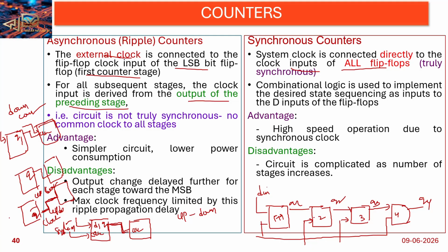So this is normal positive operation, that means active high operation. All are connected normally. This is active high, normal operation. Similarly, for active low, the up counter and down counter work like this. Q bar is connected to the next flip flop input. This is the down counter. When it is a down counter, this is negative edge triggered, neg edge.